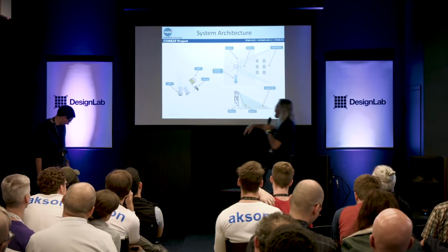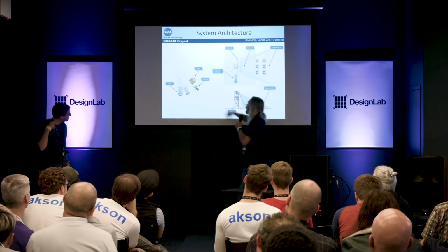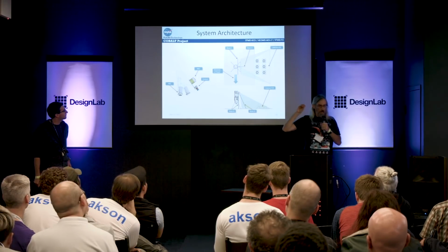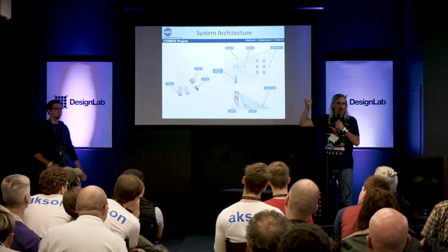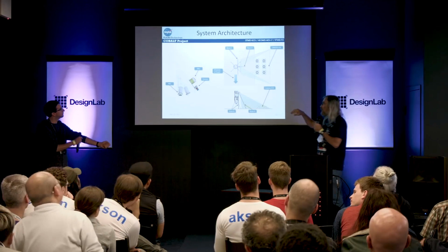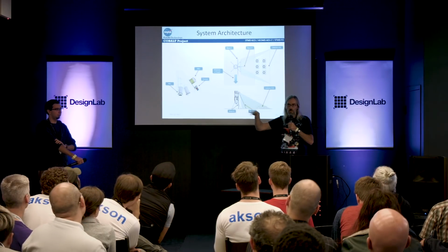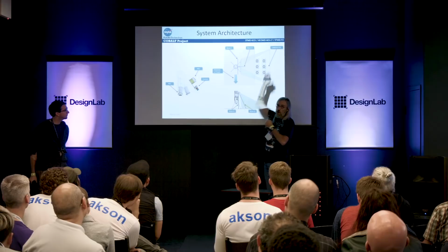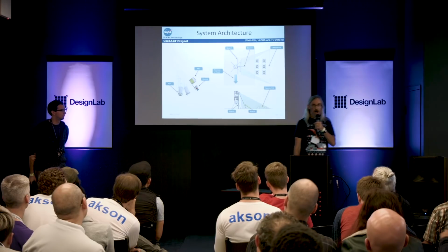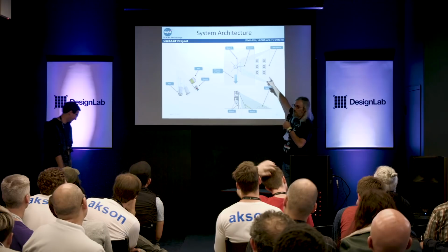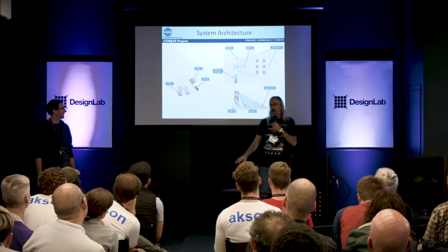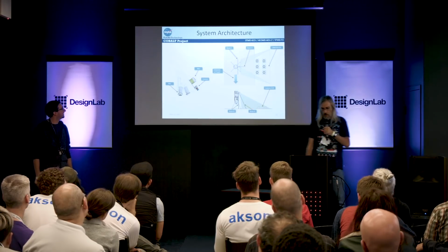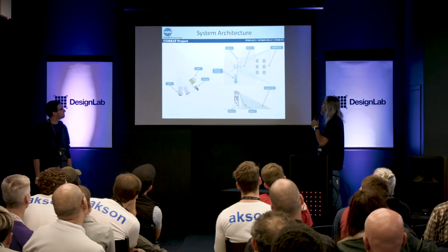Here's a little bit more stuff, details of our payload, the IMU and the LiDAR and stuff. One of the things that we have to do, like Curiosity had to initialize the inertial navigation system at the top of the atmosphere, we have to, before we take off, initialize our inertial navigation system. And we did that with a machine vision thing where we put some targets out here. Arko spent many long hours slaving away in the desert, measuring to the millimeter where all these targets were so that we can take a picture of them before we launch and do some image processing on them and figure out the orientation of the vehicle before we start.